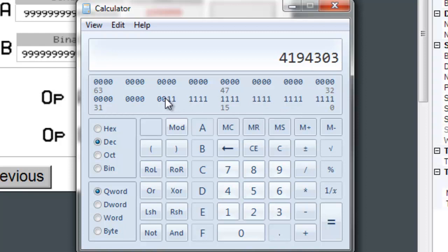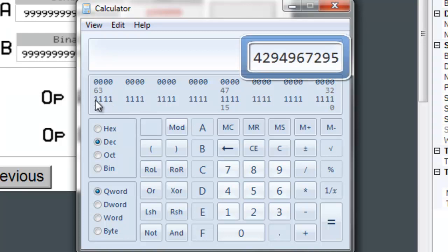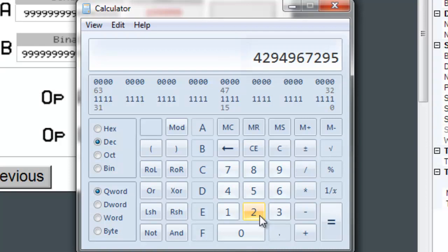So this number isn't what we expected, and that's simply because we are dealing with signed numbers on the HMC. We have to take consideration of the negative values as well. So let's divide the number we see on the screen by 2, so half the number range would be considered positive and the other half negative. And now we see a number that we recognize. Simple as that.